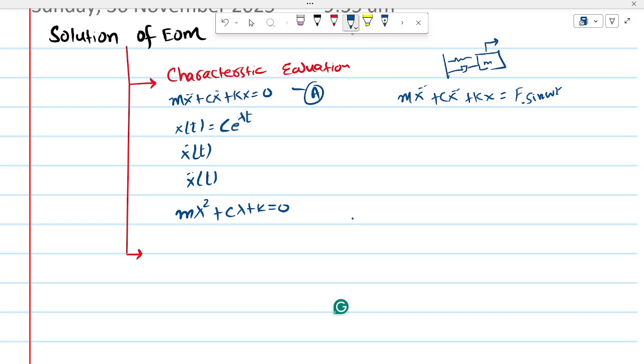So instead of finding the solution directly, you have to find a complete solution of homogeneous plus particular solution. The particular solution corresponds to the movement caused by this force, while the homogeneous one is simply the same solution as before. You add them together to find the total solution of such a system under forced vibration.